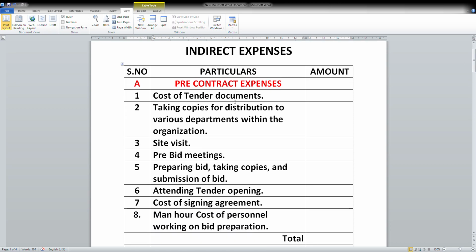Also, during the tender bids, during the negotiation, the companies will ask you to give the breakup details of costing. So you can explain the rate analysis, how you have calculated and how these indirect expenses are taken. The client generally may not be aware of all the expenses, so it is for the contractor, the quantity survey team or the contract manager to explain and make the bid successful.